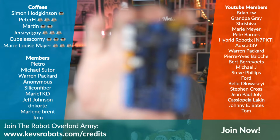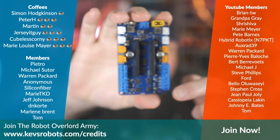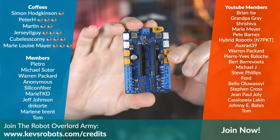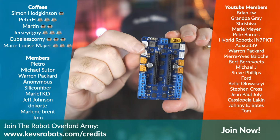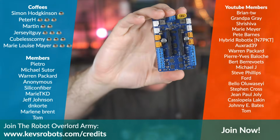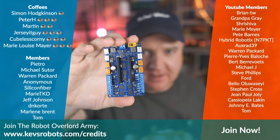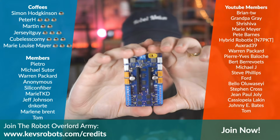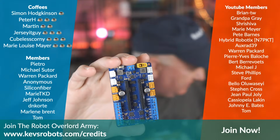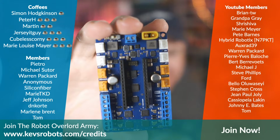I also bought this board here, which is this Arduino Nano motor carrier. So it's got all these nice chunky connectors there for motors, and it's also got these nice pins for servos. You can alternatively connect the motors up with these pins here, and you drop your Arduino Nano 33 IoT into that board. You can also plug in any of the Nano boards apparently, but you can't program them necessarily with this board. This board only supports the R4 Nano or the Nano 33, which is very unusual.